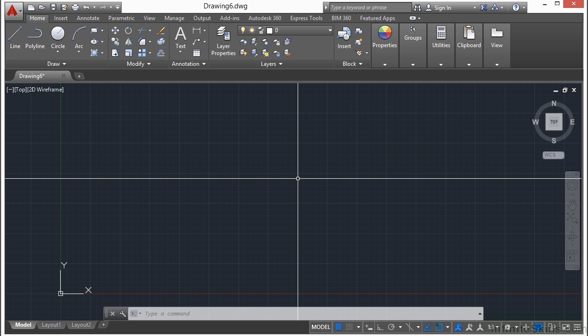Now, AutoCAD doesn't really know what those units are. It only sees generic units. Drawing units in AutoCAD are relative. It only interprets the units when you go to print your drawings or compare it with other files that you've inserted or referenced. It will translate your drawing units to fit the way you tell it to on your paper. AutoCAD will take your line work and apply a scale factor when it prints. It will take the size of the paper you're printing on and scale your drawing objects accordingly.